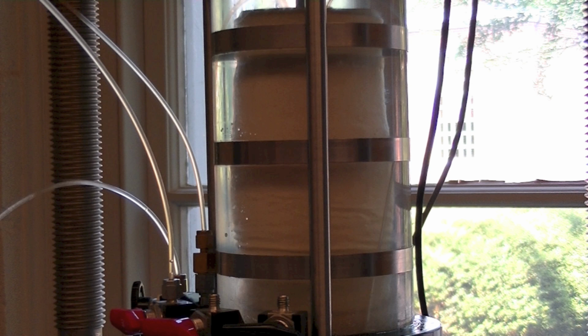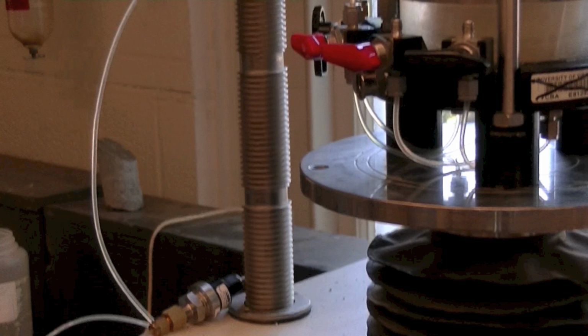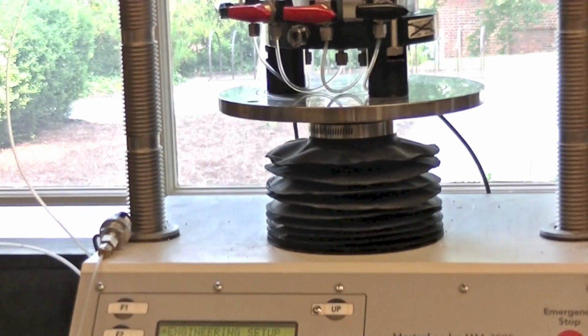Close off the red nozzle to ensure drainage does not occur during loading. Remove the black nozzle hose from the board and attach it to a pore pressure transducer. This will allow pore pressure to be read out as a sample is compressed. We expect pore water pressures to increase as the sample is crushed, for the test does not allow drainage to occur. Note that the black nozzle should be in the open position at this point.